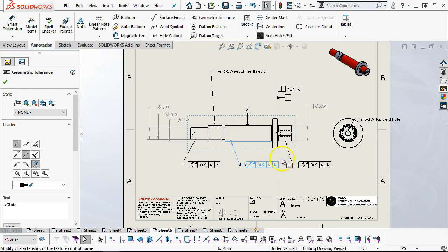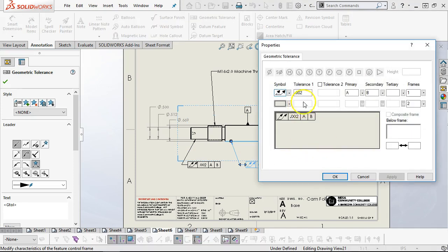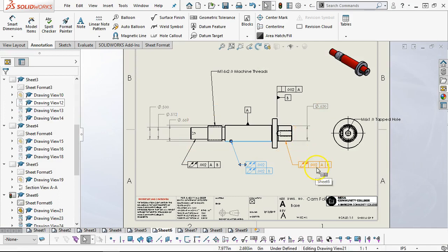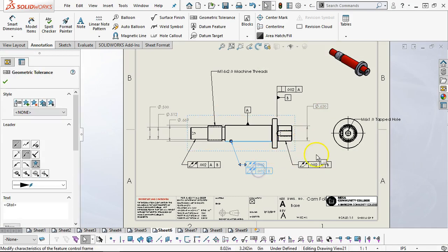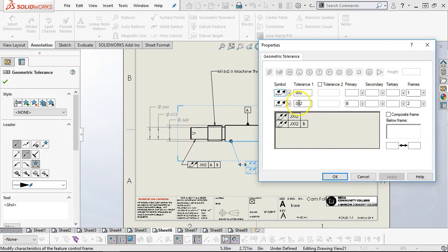for the surface, and I have to go back and look this one up because that one still kind of throws me that, in a sense, this is taking the place of our concentricity. So it can act as a form tolerance. I believe it can act as a form tolerance. And then if I'm also putting it in relation to B, I can have a second primary that it has to, that they have to be related to each other. No, I think that one takes care of that one. All right, so this is where the thought process has to go through.